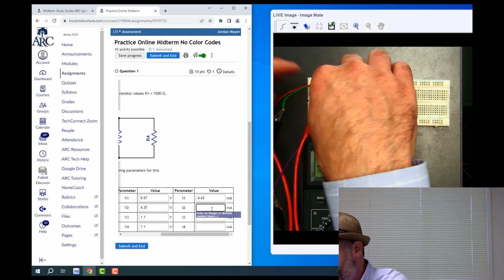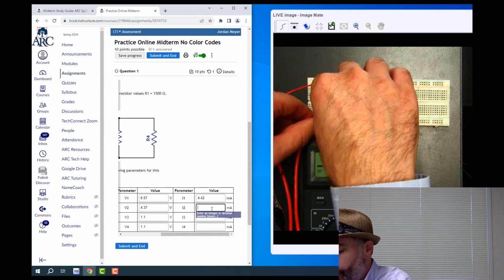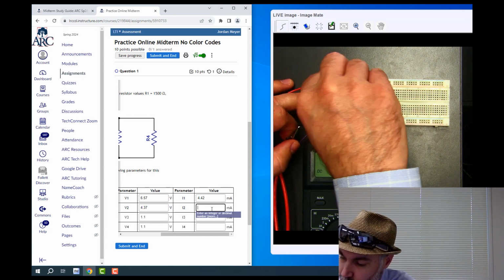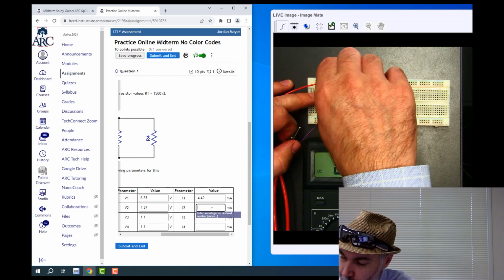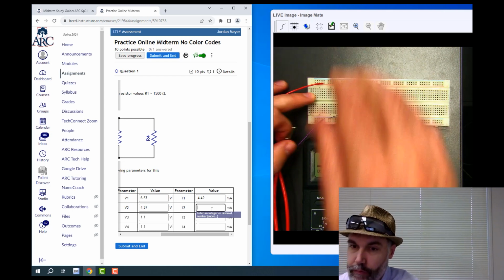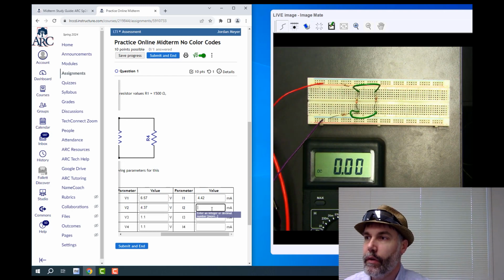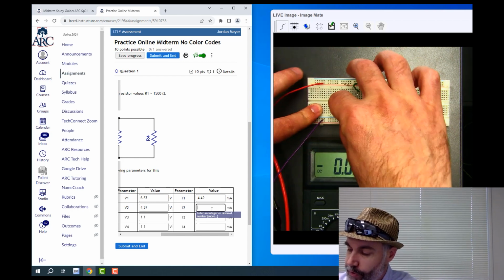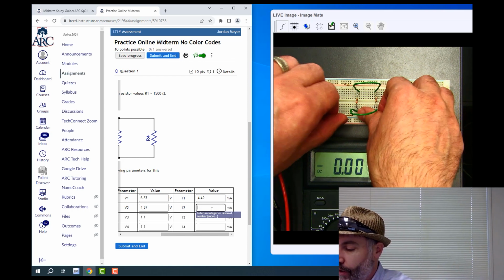And then I pull this apart, and I put the circuit back to the way that it was originally before I go on. So you just took out the resistor, put the thing in it, and then measured it? So let's do it again. So I took out one lead of this resistor. We're doing this for the bottom resistor now, R2.